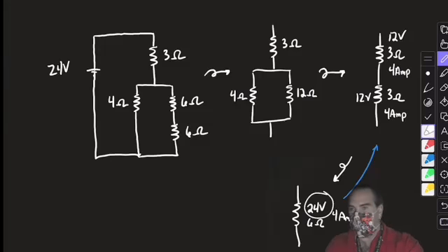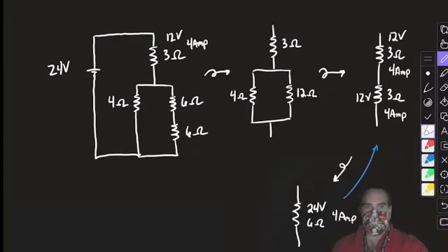Now, there was a 24-volt voltage drop. Kirchhoff's law states that I still have to have 24 volts of voltage drop. You'll notice 12 volts across each adds up to be 24. Meaning in every step, you should be able to check your work. Getting circuits wrong is 100% on you because there's so many interdependent ways that you can check your work. But also, be cognizant of when you have finished a resistor that appears in the original circuit. This is 12 volts. This is 4 amps. Especially on an exam, if you only needed information about that resistor, do not do the rest of it. There's no need.